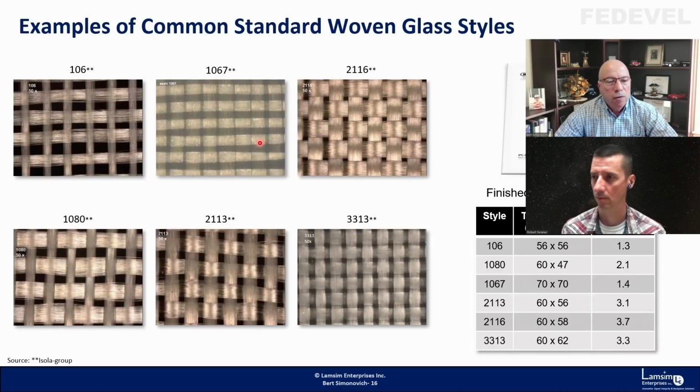They went to this spread weave glass mainly because of high-density interconnect and microvias with laser drilling. They wanted a more consistent material for it. So that's why you see the spread glass. It was really for microvias and HDI technology, but it helps us in the high speed area as well.